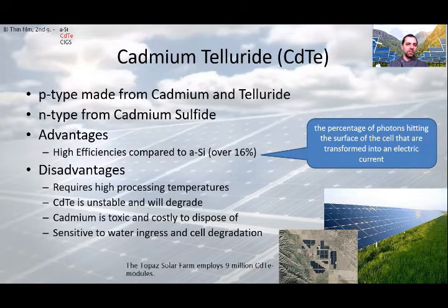On a life cycle basis, cadmium telluride PV has the smallest carbon footprint, lowest water use, and shortest energy payback time of any current photovoltaic technology. Cadmium telluride solar cells use technology which produces solar cells at a lower cost as compared to its counterparts. The payback time for these cells is also less than a year. And in multi-kilowatt systems, it is the only thin film technology with lower cost than conventional solar cells made of crystalline silicon.